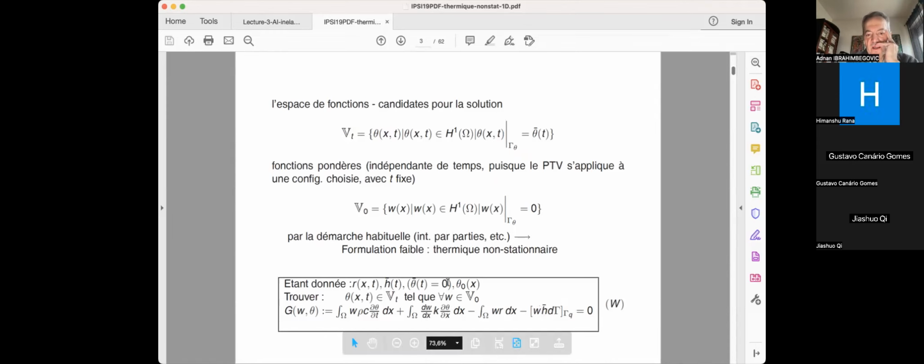And so you can compare here. If you neglect the first term here and you replace theta by u, r by b, and h by t bar, you will recognize your elasticity problem. So if I'm solving a stationary problem of heat transfer, the solution is exactly the same as 1D elasticity. If I have a code only for 1D elasticity, I can put in numerical values for, instead of Young's modulus, the heat conduction coefficient. Instead of whatever load, I can put my heating, and the displacement that I compute will actually be the temperature, and I can simply solve the problem, or vice versa.